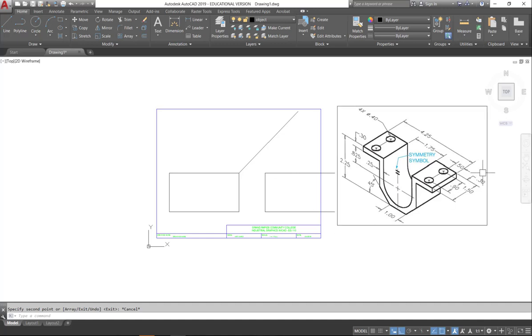And I know that my width as I look over here is 1.5. So I'm going to offset that 1.5. And I'm going to fillet that. So I know that is my right side. I'm just going to copy these two guys up. I'm going to bring them straight up till they cross. Bring that line straight across. Line from the intersection there, straight across. I don't need these lines here any longer. And I'm going to bring my lines up.